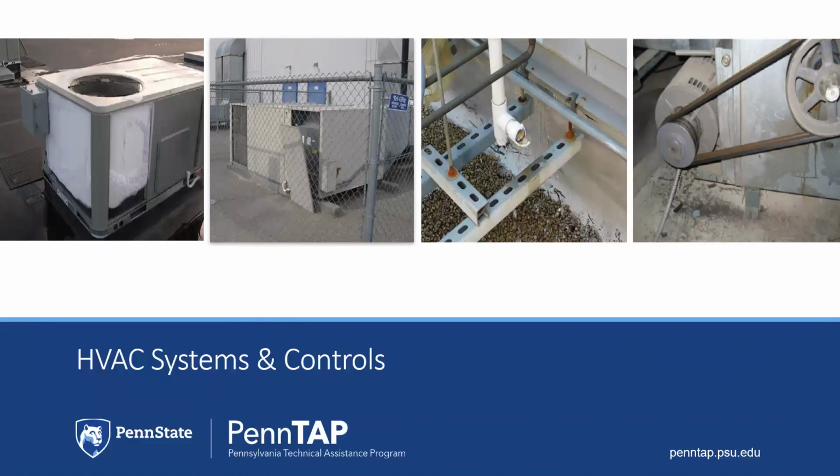Also, we have a broken P-trap, and then we have a picture of a motor that has a lot of debris around it. Many systems have motors. If there is a motor, there is vibration. And if there's vibration, screws loosen, belts stretch, and debris can form based on that. So make sure you put eyes on your equipment to see if you have a lot of vibration coming from that equipment. Maybe you need new belts. Maybe you need to tighten up a few screws. But if there's debris, try to figure out where that debris is coming from, what is falling apart.